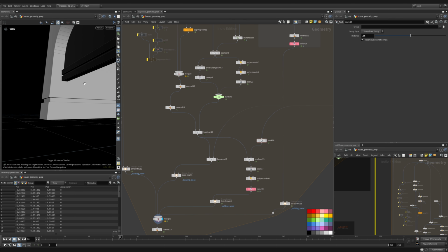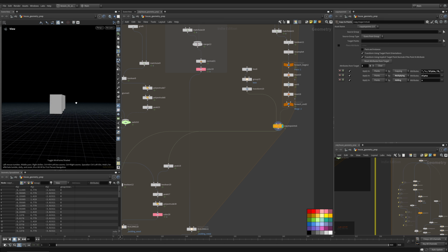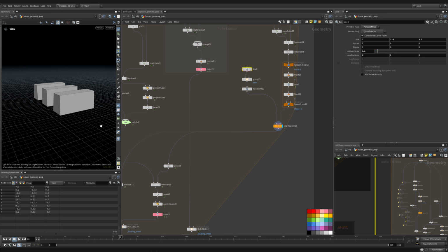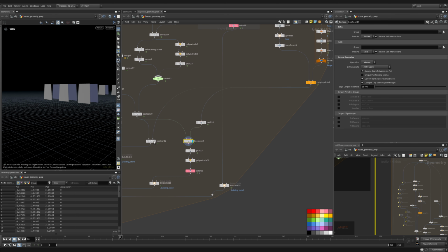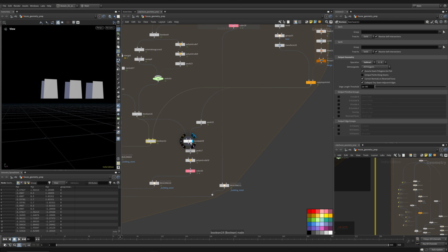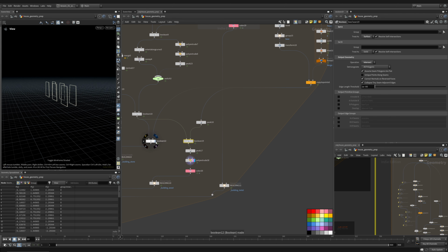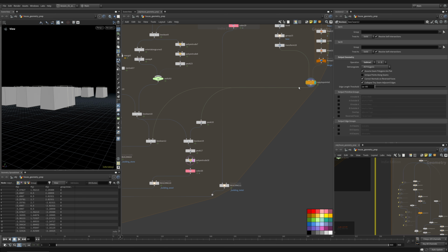And now actually, if I did want to cut all the way through, since we are learning, let's figure out how to do that together. I could scale the size of my window. And there we go. Looks like scaling my window along the Z-axis would give me enough of a cut to cut all the way through. And now this actually gives me 2 windows, but I want to get one back. So what I can do to fix this